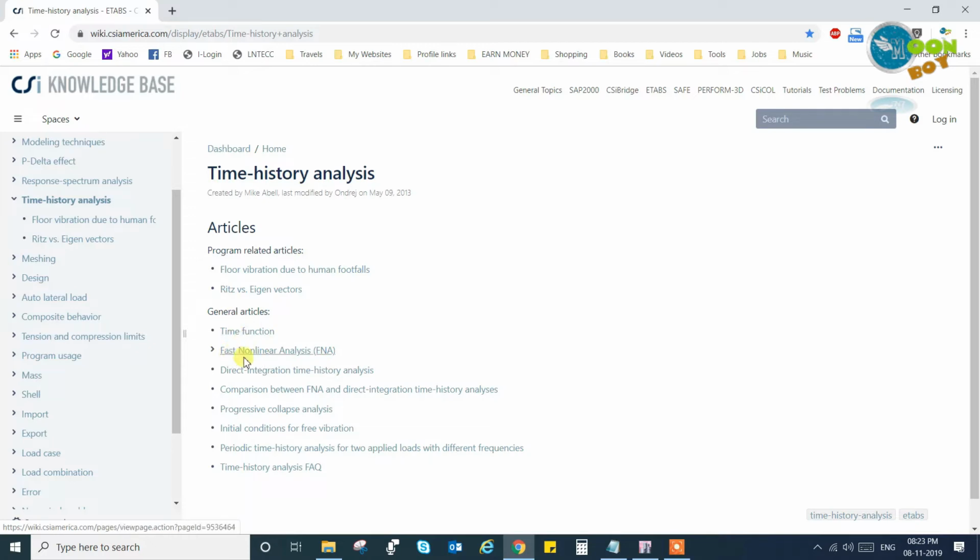There are two methods, FNA and the direct integration method, and you can find which is best here. You also have progressive collapse analysis, which you can do using time history, and initial condition free vibration. FAQs are also available here, so everything you want is available here.